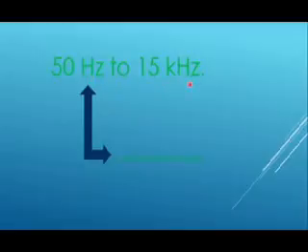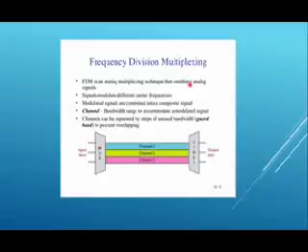Stereo sound is also available in TV, and the multiplexing method used to transmit two channels of sound information is virtually identical to that used in stereo transmission for FM broadcasting. The picture information is transmitted in a separate carrier located 4.5 MHz lower in frequency than the sound carrier.